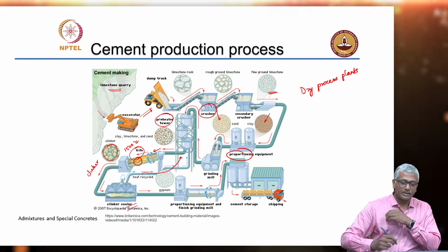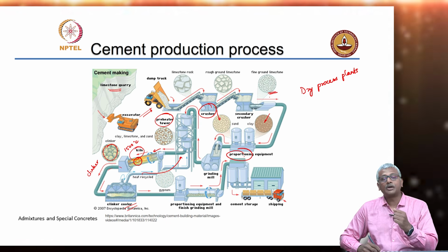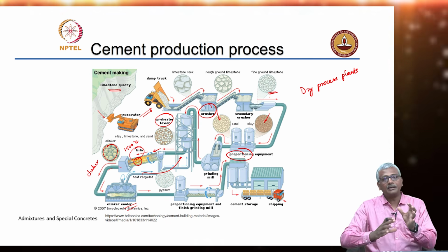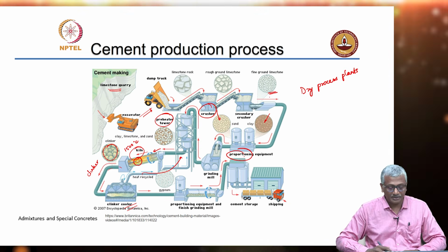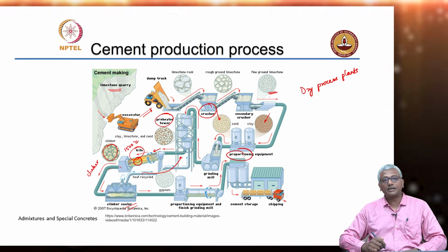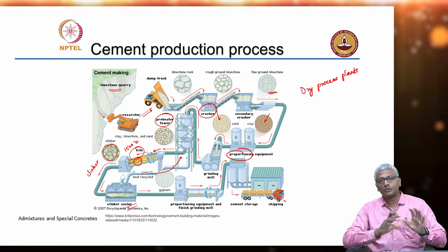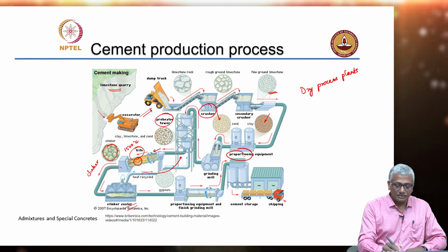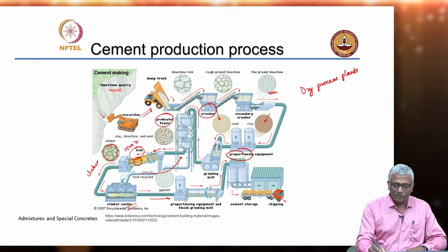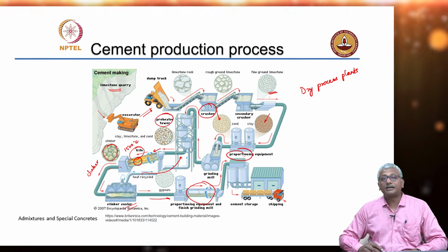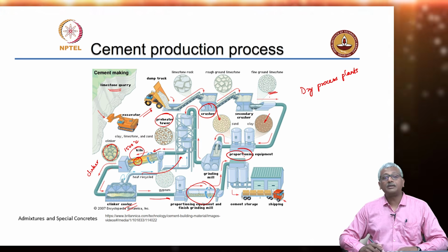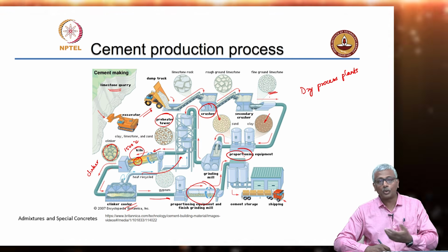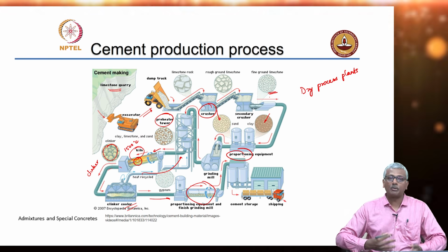what is shown here, that is the clinker, basically comes out and has to get cooled rapidly in the beginning and then in a controlled manner after that. So, the clinker cooler is an integral part of this entire system. It has to cool down rapidly in the beginning and then slowly, and then it is taken to the final step of cement manufacture, that is the grinding, that is done typically in a ball mill, or today there are much more sophisticated roller presses that do a much better job of grinding.